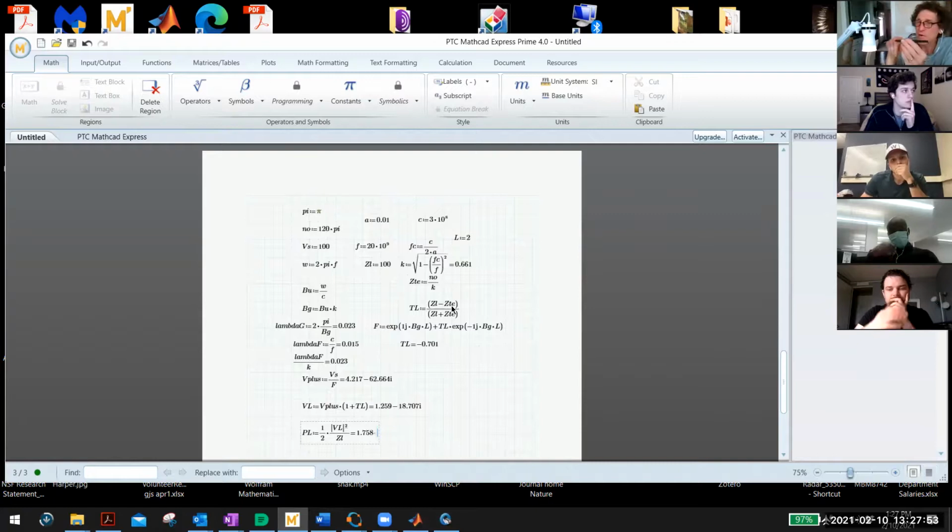If you have a coax cable, the length of the coax has to be at least 1/10 of a wavelength for it to start behaving as a coax cable, where the characteristic impedance is important. If it's shorter than that, it looks like two pieces of wires. That's the rule of thumb. So it's got to be at least 1/10 of a wavelength long to start having its own characteristic impedance. Otherwise, it's not an abrupt change, but that's the rule of thumb.